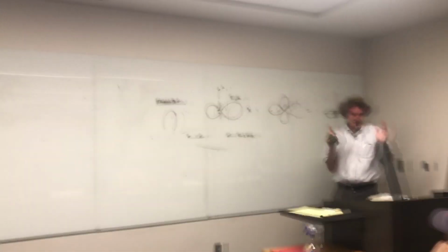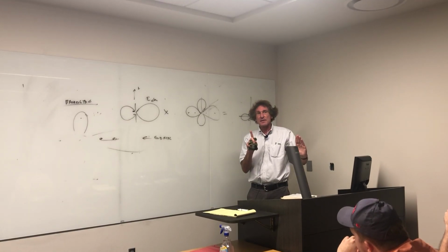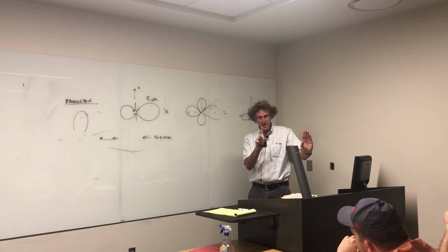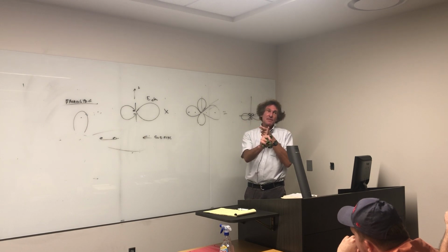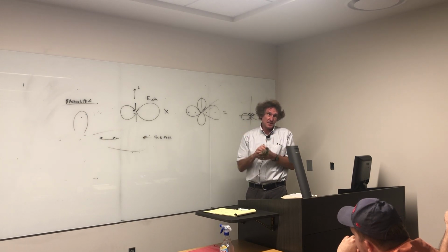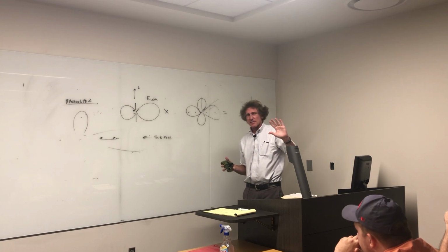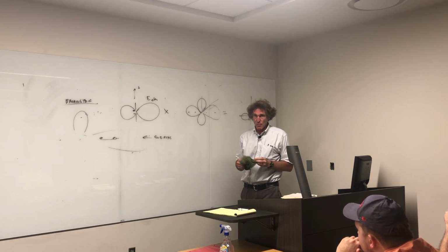delay. And what I said was when they add length of lines, that's time delay, but there's a way to do this electronically where they take whatever the signal is that's going to feed the first antenna, and they literally take that signal. Now, this is going to be with FPGAs, all right? So they get an exact memory of this after it's sampled at twice the highest frequency of interest. Then they take that and they literally shift it back by any amount of time you want. So that whatever appeared at t equals 0 will appear at t minus the time delay, and then you can feed the time delay to the next one. That's a little advanced now, but I'll tell you why that's so important.